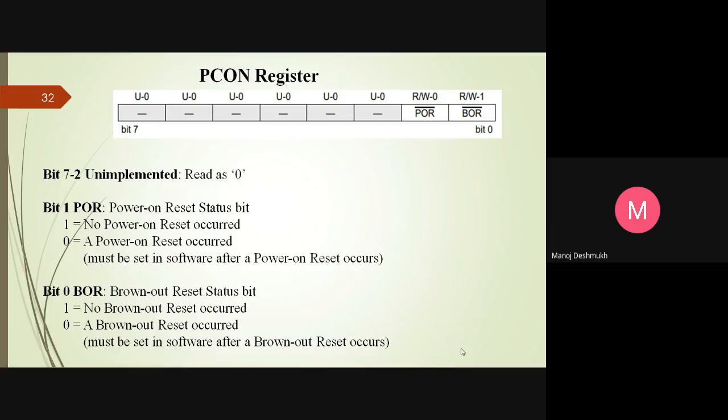Whether DIP, SMD, or PLCC, based on these various packages, leadless, leaded, or SMD, three major types related to the pin configurations, the minimum required voltage for a PIC controller is 2 volt. So when the supply voltage reduces below that, less than 2 volt, in that case brownout reset is detected or occurs.